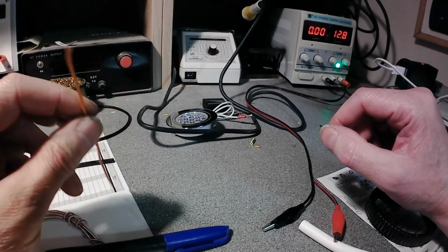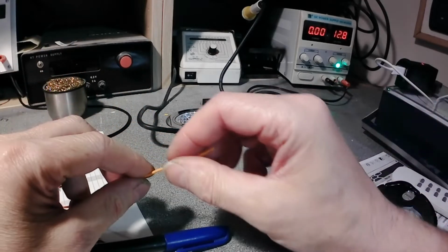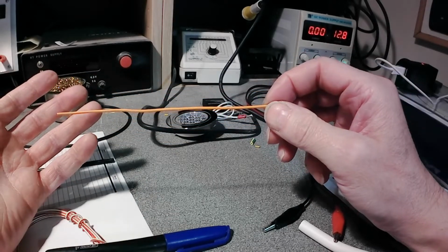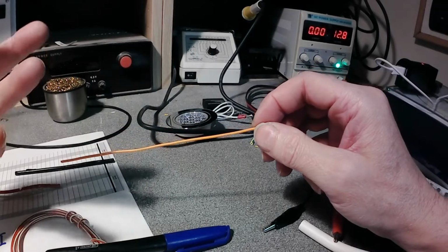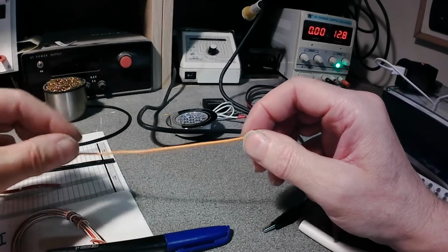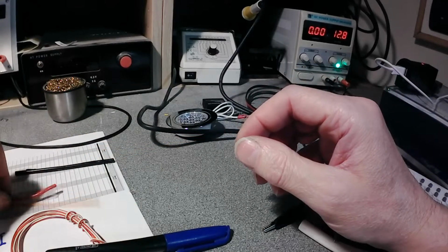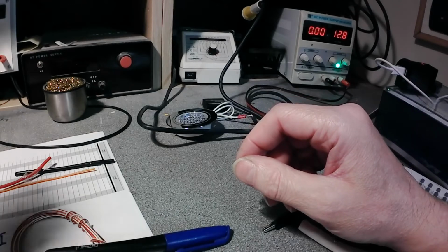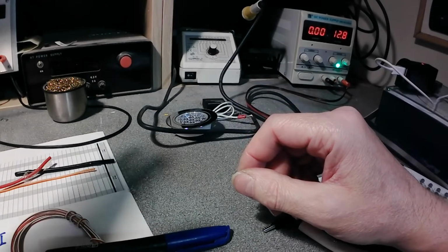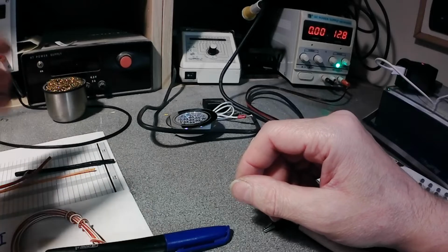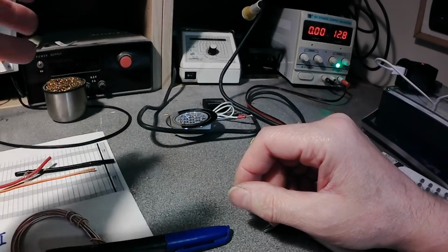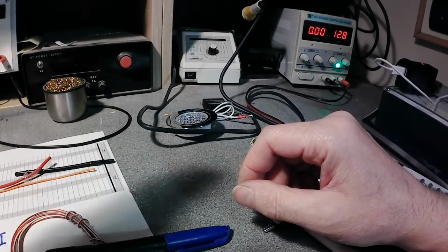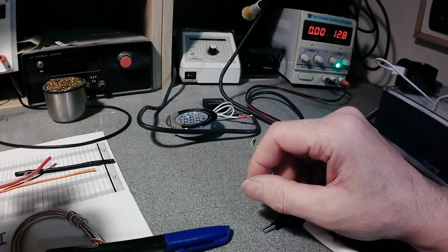It's still far away from the edge of 10 amps or even 16.5, but in reality it operates more like 10 amps. So everything we connect, like a motor or blower, we have to check the power consumption in watts. Sometimes producers give the amperage also, so it's easy to check, but if not, we can calculate it from power.